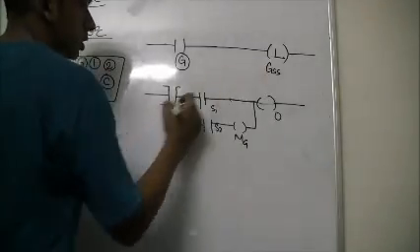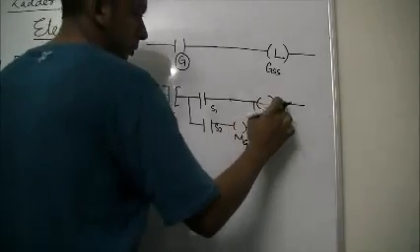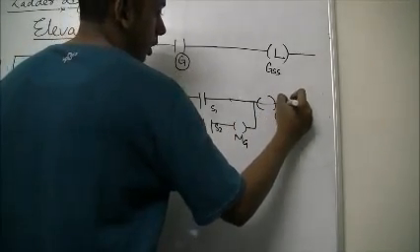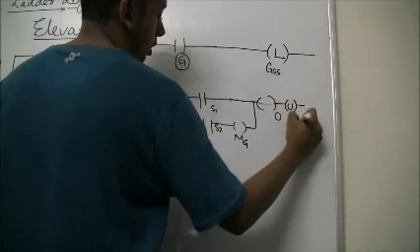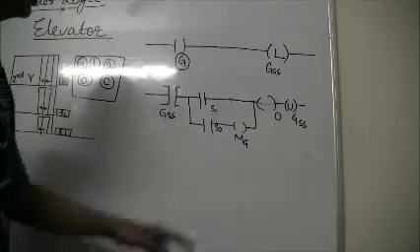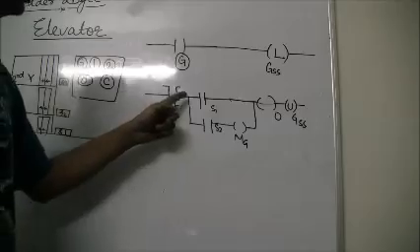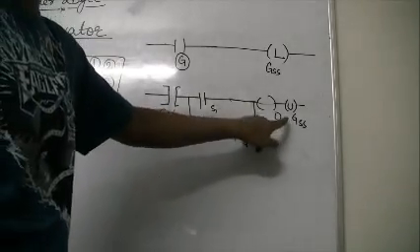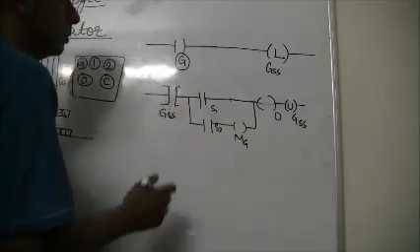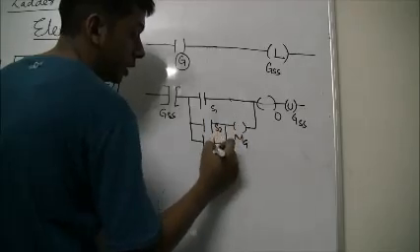So this would be GSS, right? And after this, it unlatches GSS. Now if it doesn't unlatch GSS, this output would remain on and the door would remain open forever. So we need to close it back. So unlatch GSS would close this rung. Similarly, we need this also for S3.